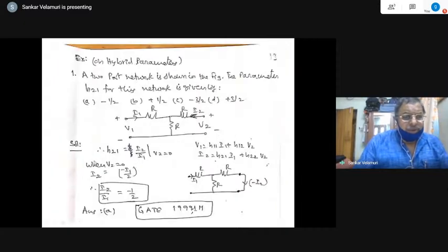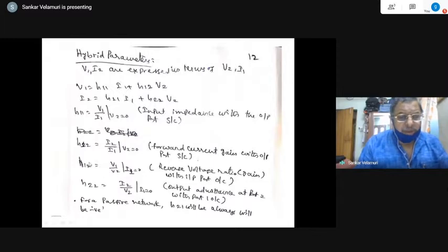So now I would like to give small examples of this one for computation. I hope I told many points, but sometimes it may be confusing. And while writing, we have not taken this minus sign, but I2 will always be negative. You will obtain this H21. That is why for a passive network, H21 will always be negative, as that has been stated.